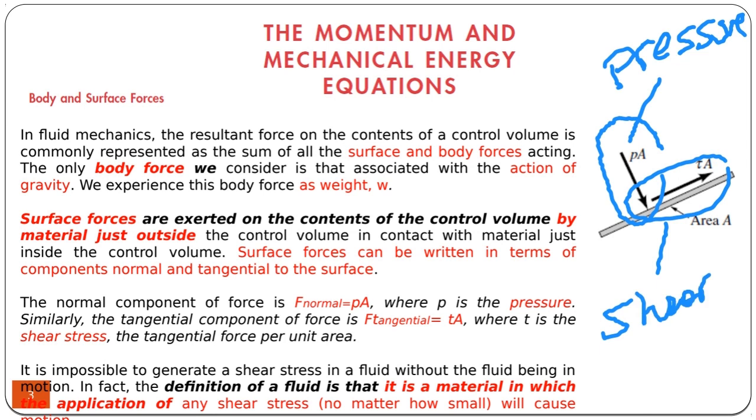So as a resultant of them, the fluid can apply a total force on a surface. As a matter of fact, if there is a tangential force, then the fluid must move. So no motion, no shear. The water inside the glass does not have any shear force, but when you start to pour it, the shear will develop. So shear means there has to be some motion inside the fluid.